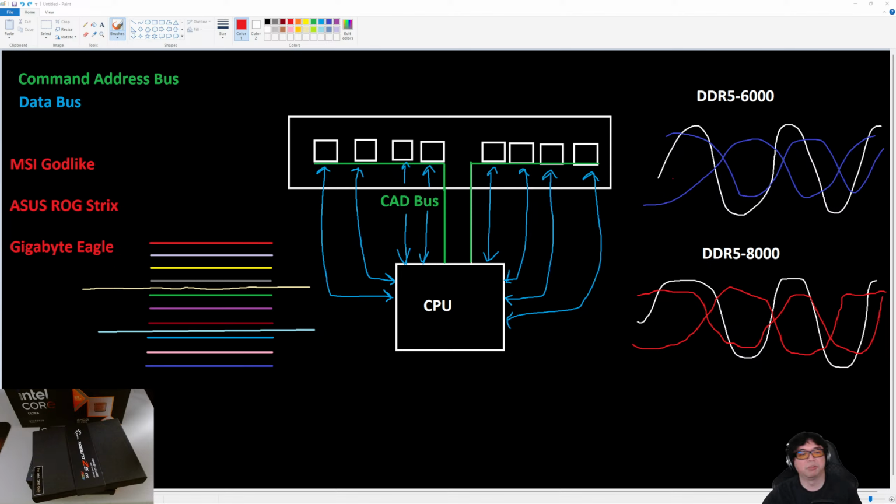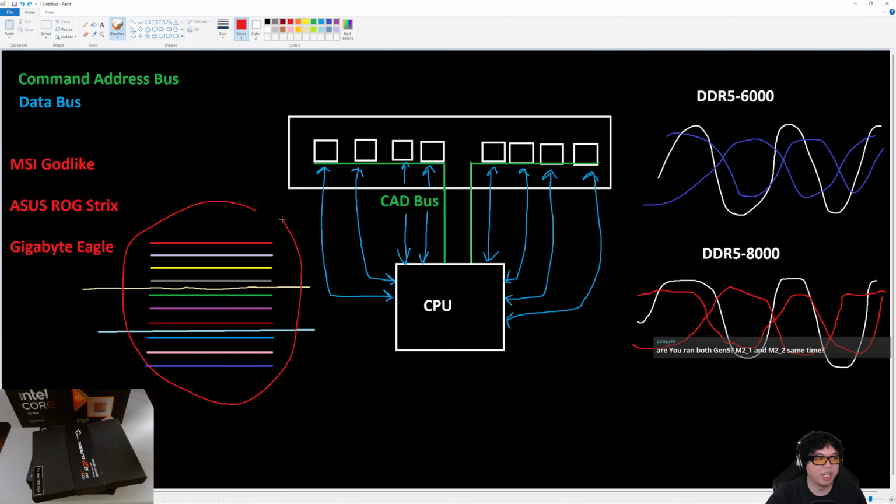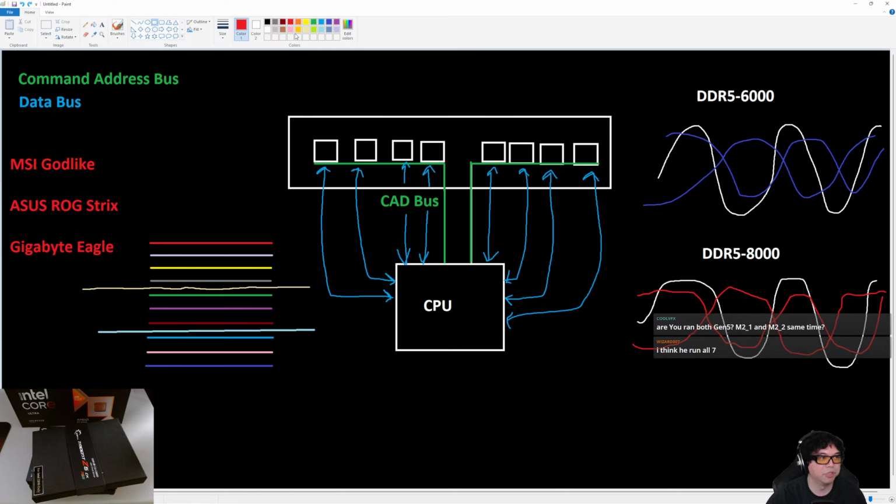Okay, so now we can talk about CUDIMM, because we've explained why you can do higher speed with better isolation, with lower temperatures, and maintain stability. But now, what happens with CUDIMM? CUDIMM introduces a new component to the DRAM itself.